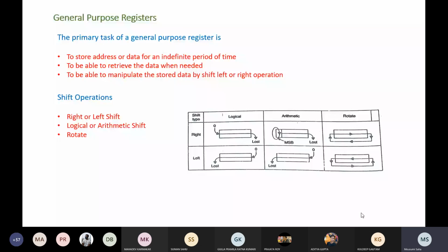Now you can understand the logical right shift through this table where I have drawn the figure. Right shift means that the LSB of your number will be lost, and the MSB will be vacant at that moment, and that will be filled with zero. Okay, so this is the logical right shift. On a right shift, obviously, the left shift bit, where will it go? It may be lost. Sometimes it may be controlled with the help of some other flag registers.